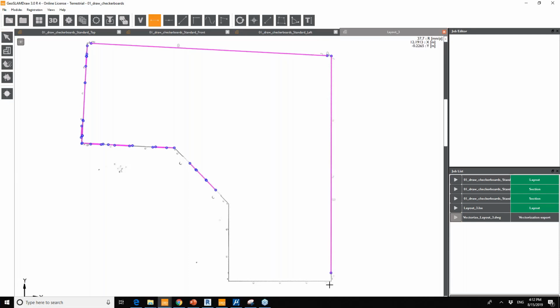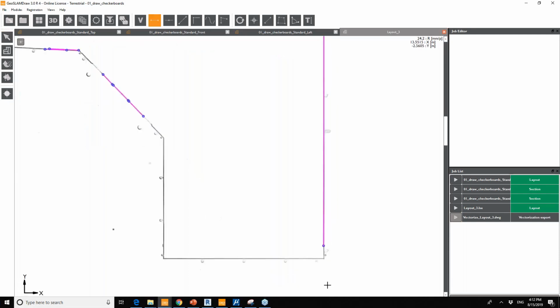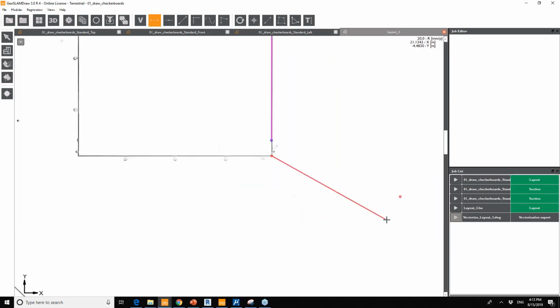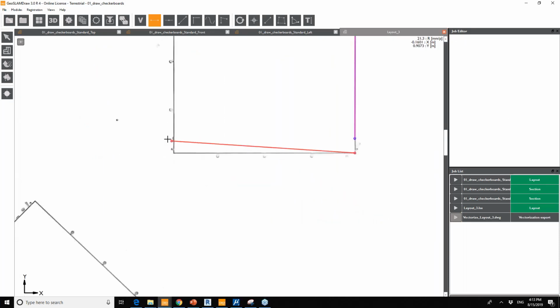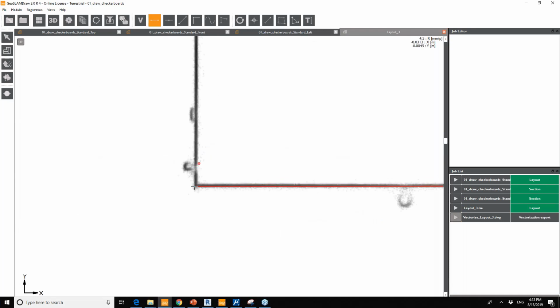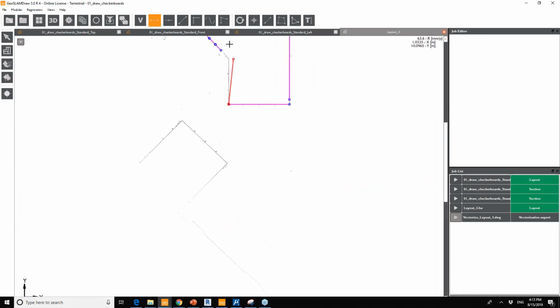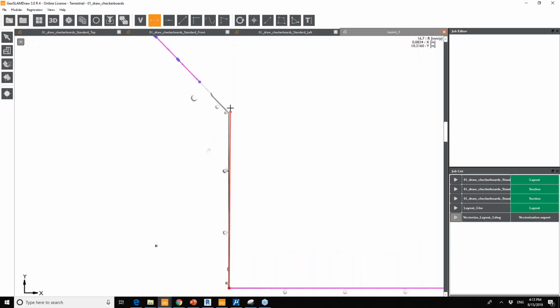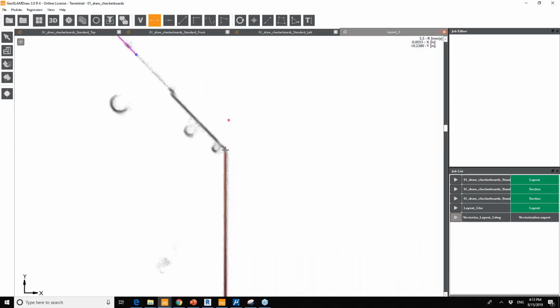And you can also create the lines manually at the vertices, intersect between the lines, which might be easier if your point cloud is aligned first, so you can actually hold the shift key and create the straight lines of the buildings or the rooms.